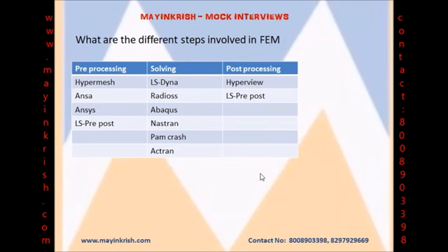The final phase in finite element analysis is post-processing. After completion of the solving, any solver will give some output files. Post-processing begins with a thorough check for problems that may have occurred during solving. Once the solution is verified to be free of numerical problems, quantities of interest such as stresses, effective plastic strains or permanent deformations, and reaction forces have to be checked. The best post-processing tools in the market nowadays are Hyperview and LS-PrePost.